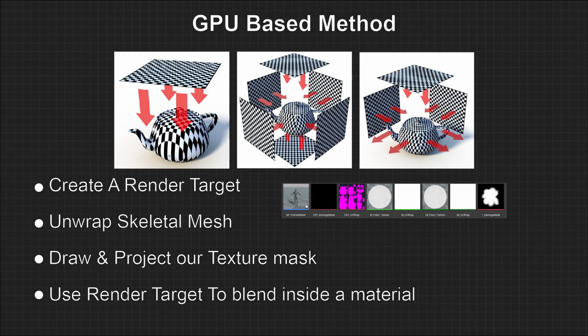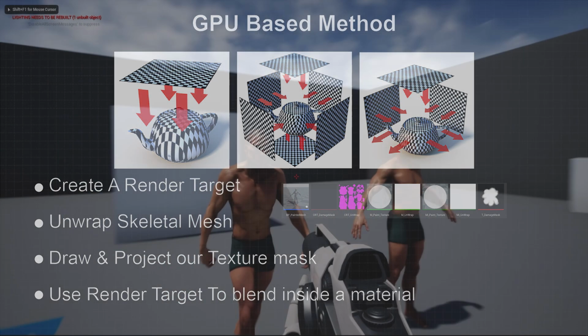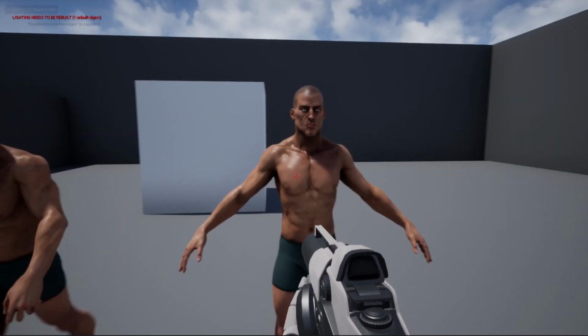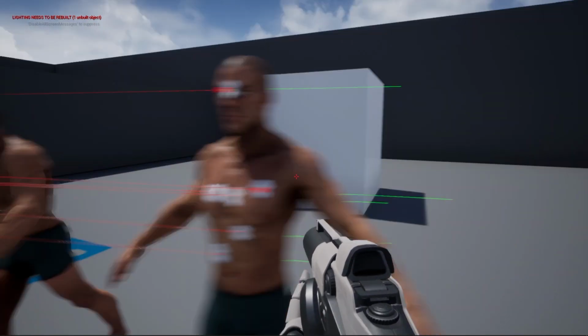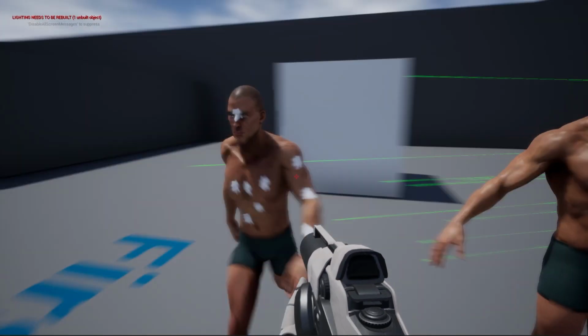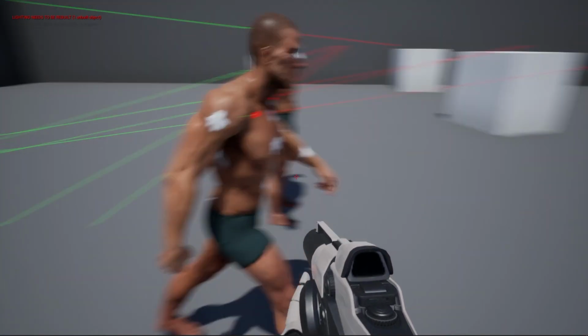Hello everyone. In this video I am going to explain a simple technique to draw textures onto a skeletal mesh inside Unreal Engine. Now there are several tutorials on the subject already, however I found that no one really describes the technique to draw with an actual texture. Currently available plugins rely on some hacky and slow C++ code just to extract the UVs.